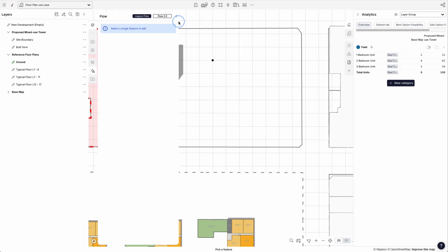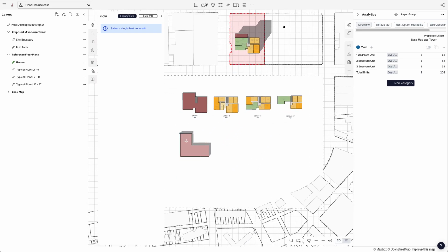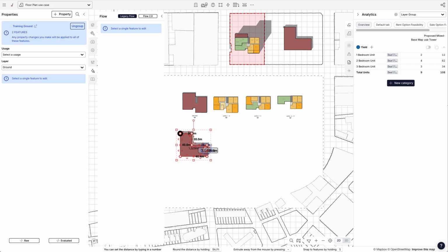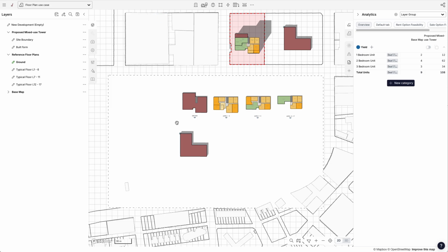And then I'm just going to minimize this panel so I can see my floor plan. I'm going to navigate. So I'm in my crosshairs and I'm just going to select my floor plan. And you can see straight away that it has referenced that group. And just to double check that, if I start to adjust that, yep, we can see that's all adjusting and linked as expected. All right, so we've got our first, I'll just close out of this. We've got our first ground floor in.